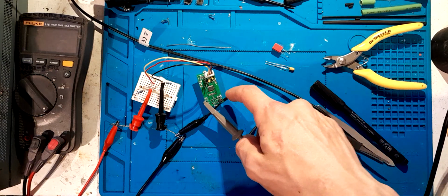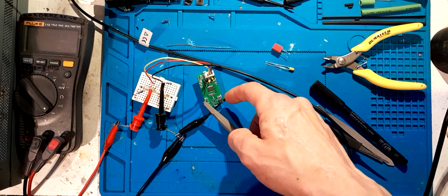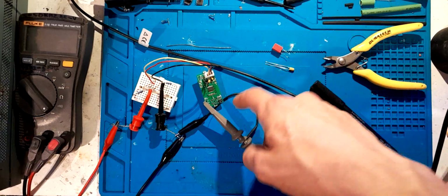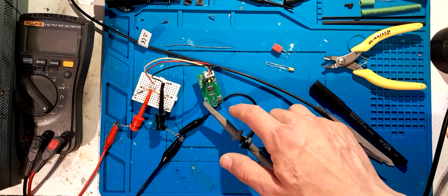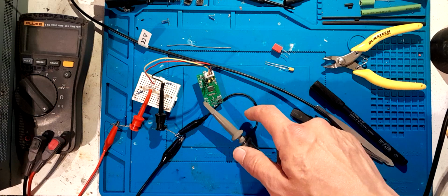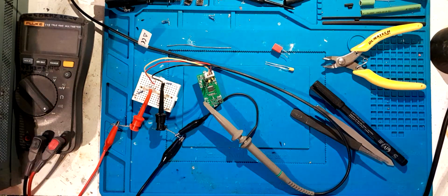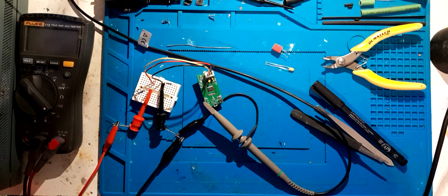So, oh yeah, I did a bit of research on it, and it looks like these devices can handle a bigger capacitance on the output. There are some case scenarios where they can't, so just in case, actually, the thing it's being powered off of has got the 470 microfarad cap on the output, but it is powering relays.